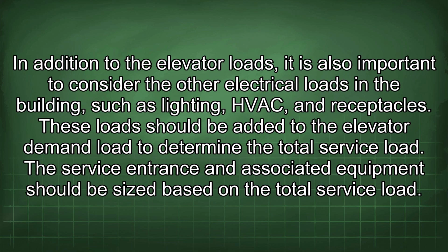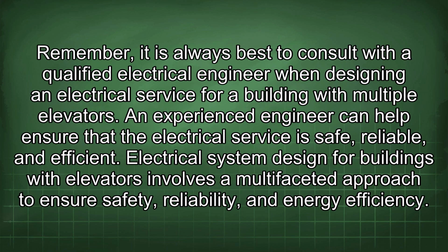In addition to the elevator loads, it is also important to consider the other electrical loads in the building, such as lighting, HVAC, and receptacles. These loads should be added to the elevator demand load to determine the total service load. The service entrance and associated equipment should be sized based on the total service load. Remember, it is always best to consult with a qualified electrical engineer when designing an electrical service for a building with multiple elevators. An experienced engineer can help ensure that the electrical service is safe, reliable, and efficient.